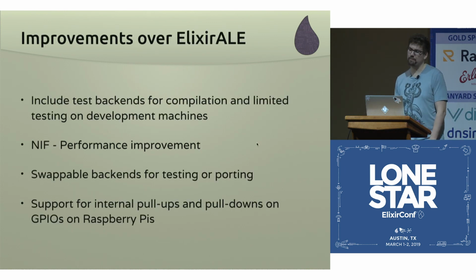But there's been a lot of great improvements over ElixirALE, including that it's now modularized in a way that there's an included test backend for compilation on host. These things are meant to run on embedded Linux, and if you're not on embedded Linux, like obviously twiddling a GPIO, there's no pins on these laptops. So it doesn't really match up that way, especially on Mac OS since it's not embedded Linux. It'll swap out the backend adapter for a test one, so you can mock it, and then you can still write nice verbose test suites in Elixir.